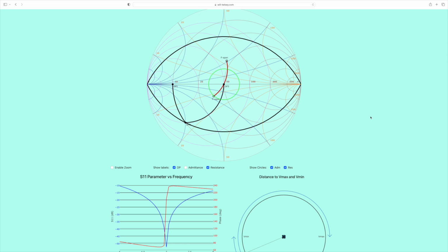And so you will see, as we are on the high pass filter at the moment, you perhaps won't be surprised to see that the 1 megahertz above our frequency, all of that fits into 1.5 to 1 SWR, whereas below it we don't get as much there, and that's because this is a high pass filter, so it's going to pass the higher frequencies through more readily.